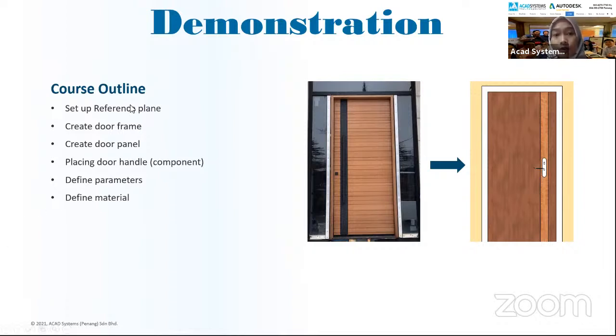After the reference plane, we will create the door frames, then the door panels, and then we will place the door handle by adding the component. After we are done with our door family, we will define the parameters of our door.